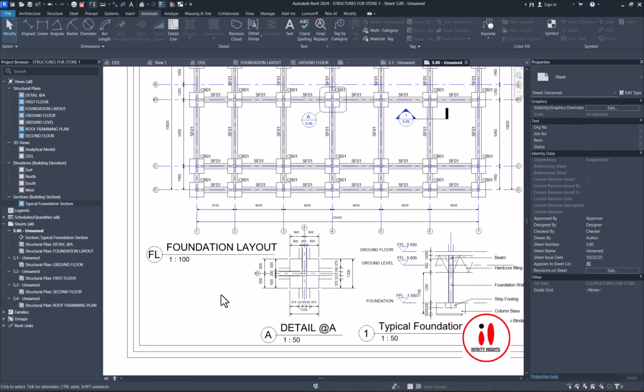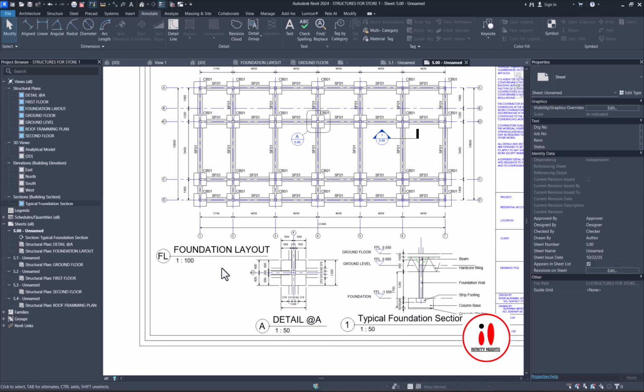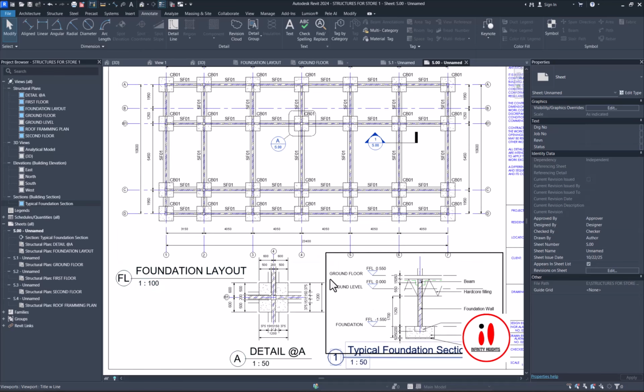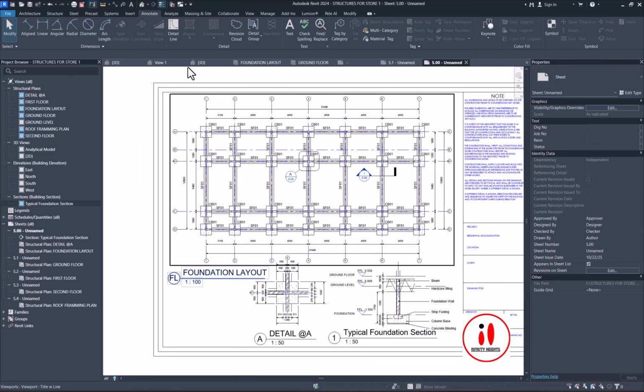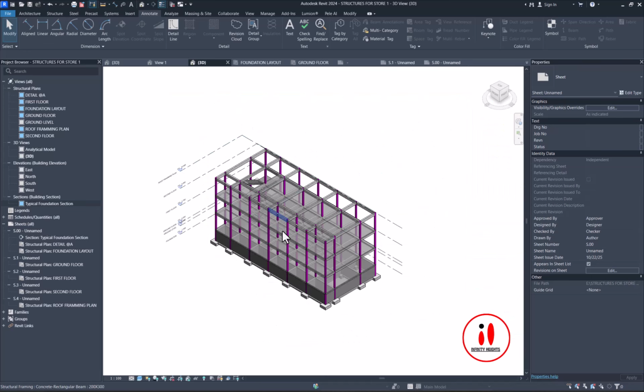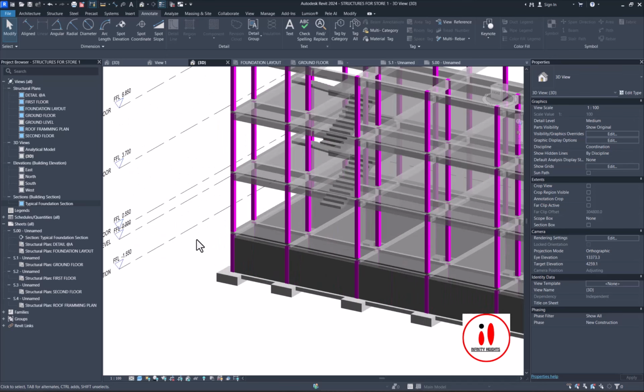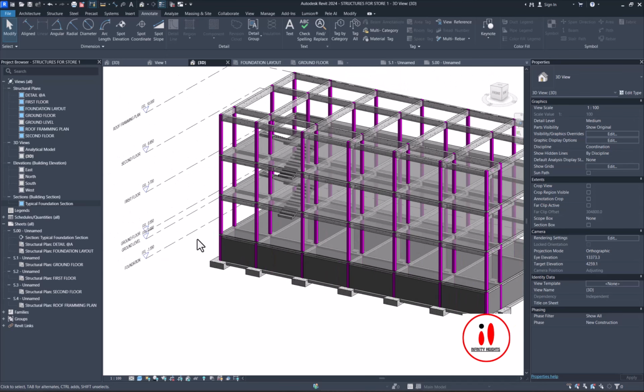Okay, so I want to indicate that the veranda is stepped down. Yeah. Oh, you have to do it in your slab. Then you take a section. Where is the front? There is the front. So when you are doing the slab, you have to end this one slab here. Then you create another slab. Then you lower it 150. When you are done, you take a section two for them. They will indicate that this one is down.